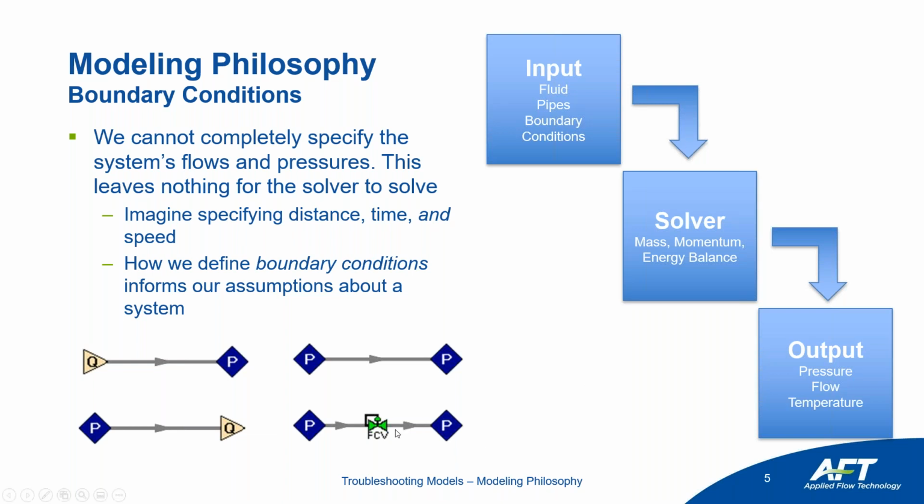So now, downstream or upstream of this, you're matching that field data, which might feel good, but what you're doing is introducing essentially another boundary condition into your model that wouldn't exist in the real system. So if you don't have a flow control valve in your physical system and you're just using it to try to calibrate and match systems, generally that's not a good idea, because again, imagine if we're trying to add a valve or open or close a valve slightly, this flow control valve is always going to set the flow rate at that point.